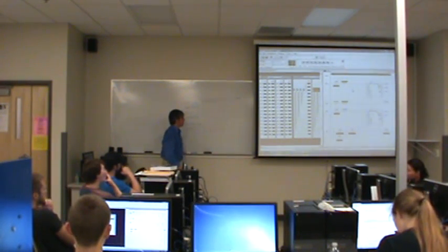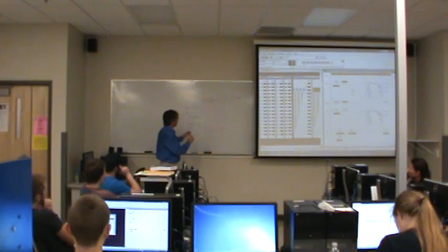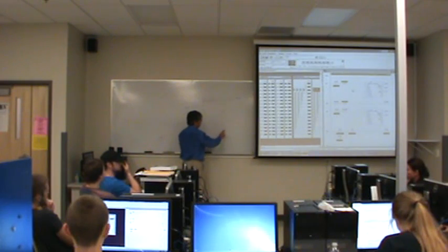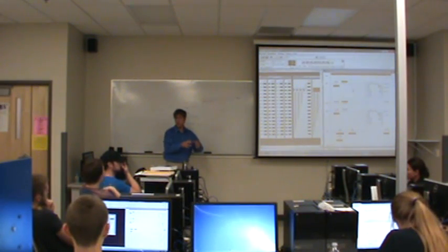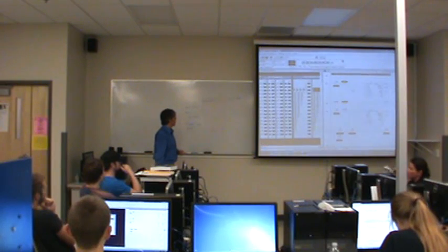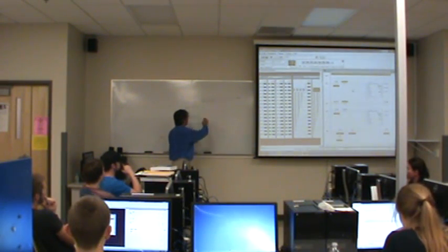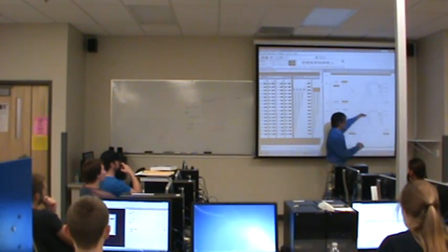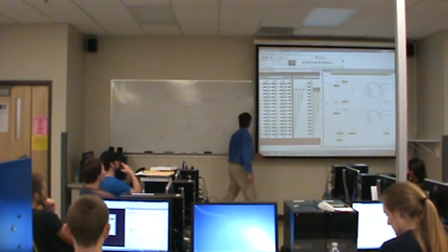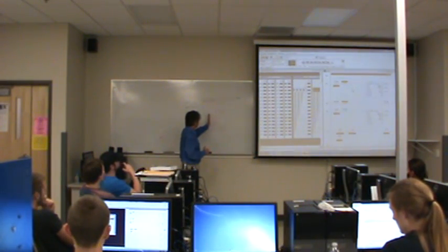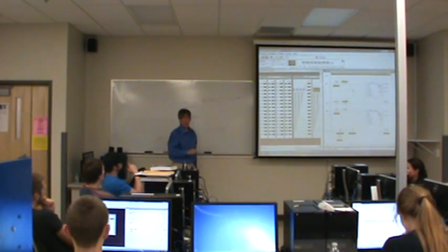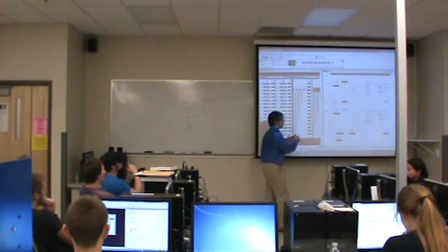And what's nice about this, it's rare that we have the pump, or two outputs, on at once, but it does happen. For example, in the spin cycle, the pump has to be on, so that we can pump water out as it gets wrung out of the clothes. Okay. But what this instruction will do, we'll put a pattern in memory of outputs, how we want them to be triggered, and this sequence output will just move from one line to the next as we tell it to. It keeps track of what line it's on, and as you trigger it and tell it to move to the next, it goes to the next and sets the outputs just as you have in memory. Okay? Does that make sense? So this basically runs through the list and puts them out on the outputs.